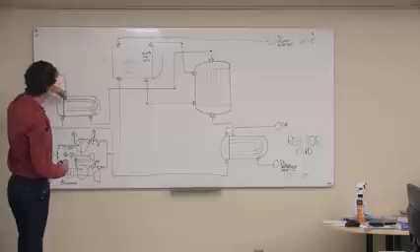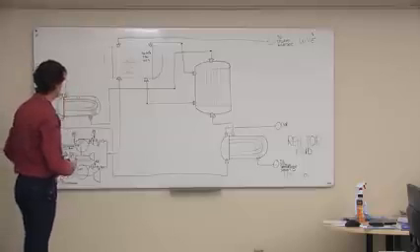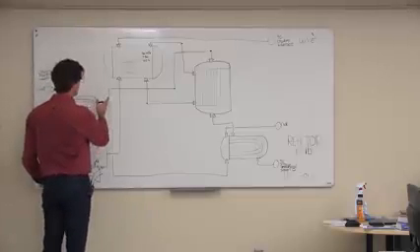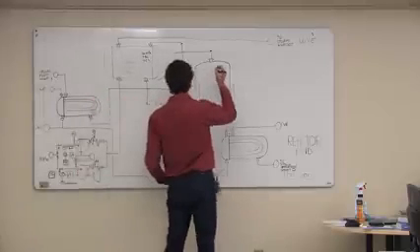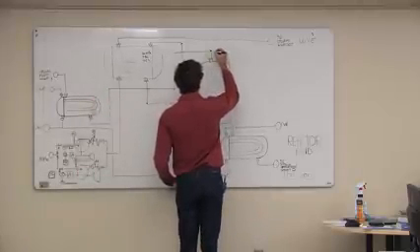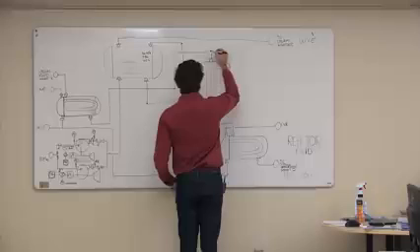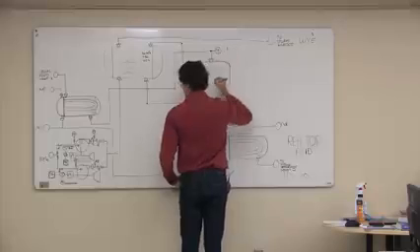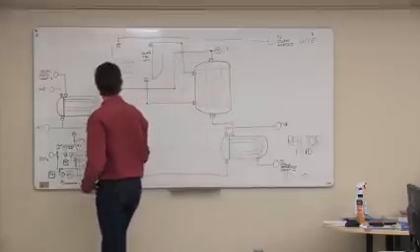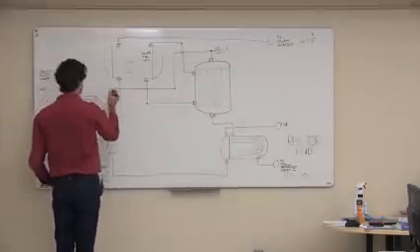It's coming through, it's being cooled through this heat exchanger. We might be interested in what the actual temperature is going into that heat exchanger. Going into the reactor. So we probably want to measure the temperature here. We may not actually control. Changed my mind. We do want to control that.